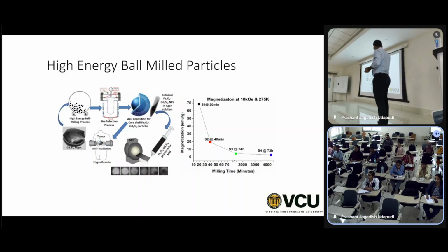But the point I want to highlight is you use arc melting, make a big ingot, make sure it's chemically pure, like it has the 5-4 phase, then anneal it, and then make powder out of it. Once you have the powder, you can do powder bed fusion, or you can use LENS.